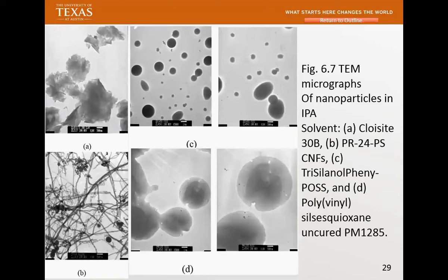The trick is this: when you see that, you cannot tell how good the dispersion is. When you cut the clay this way, you see the thickness. Then you can see how well dispersed it is. Unfortunately, you have to cut a lot of samples in order to see this orientation. The XY plane, as I call it, versus the thickness direction, Z. If you cut a sample like that, you cannot see. You may say, yeah, they're stacked together, but it's not a good way to see how well dispersed. You need to cut it in the Z direction, the thickness, and you will see. I'll show you some other examples.